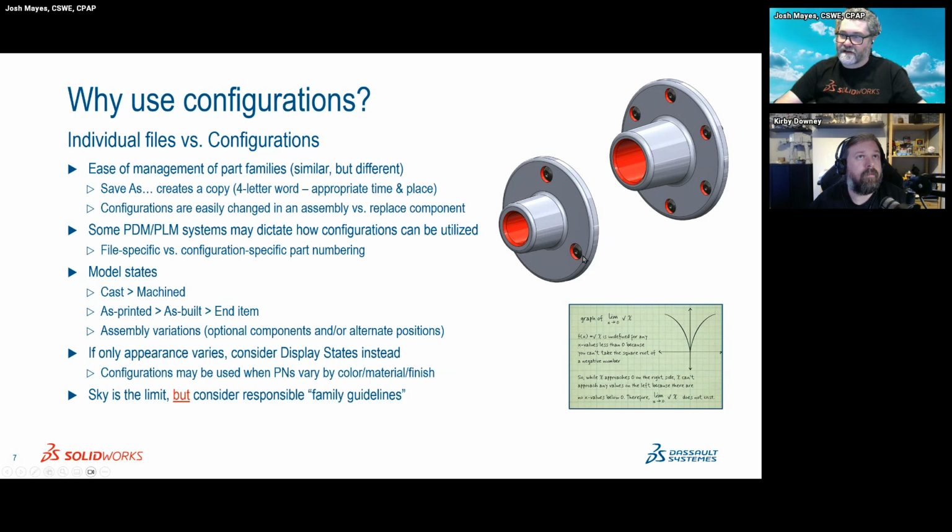And that was done, as you'll see in the demo later, with a single part file for the bracket, a single part file for the screw, and the part file, the screw both have a design table, and the assembly has a design table. So everything can be driven with those 3 models in that example.